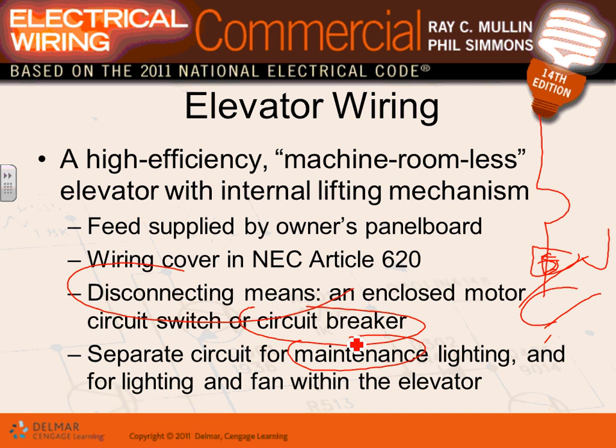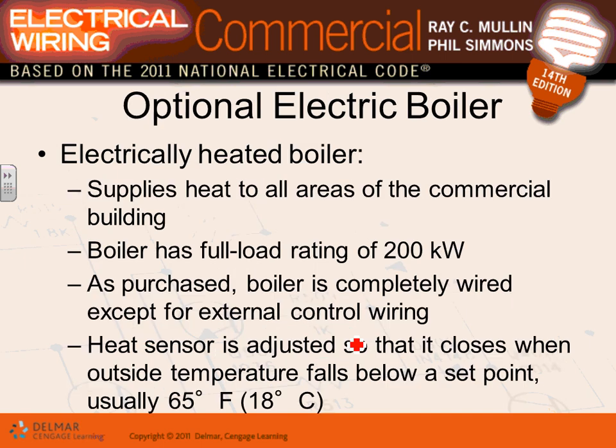But they typically need GFCI receptacles, guys, in the machine room. They need a dedicated circuit for those receptacles. They need a circuit for the lights in that machine room, and a circuit for the car itself that goes up and down, for the fan as well as for the lights. So be aware of that one.